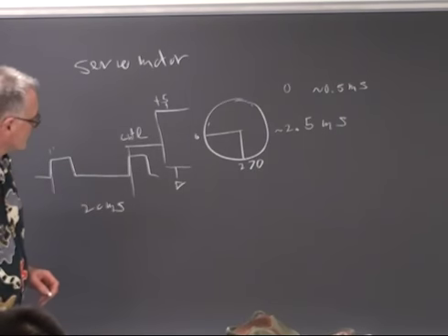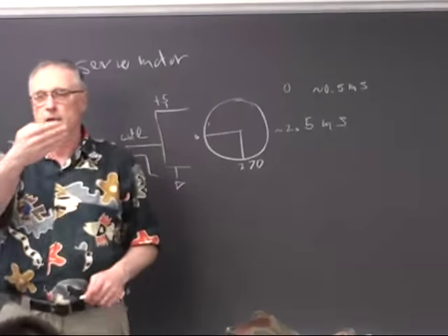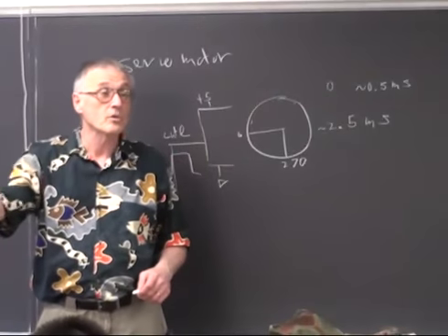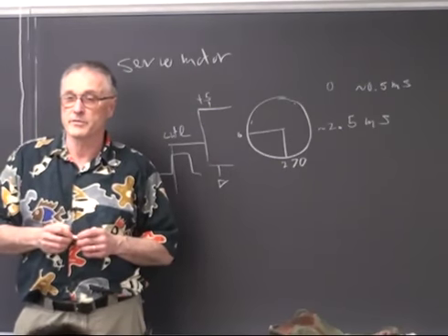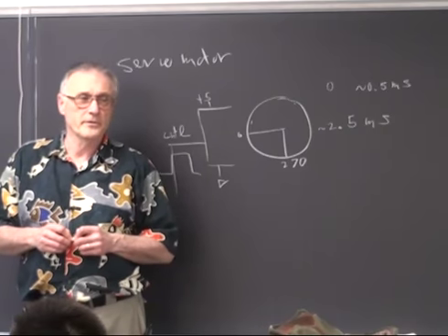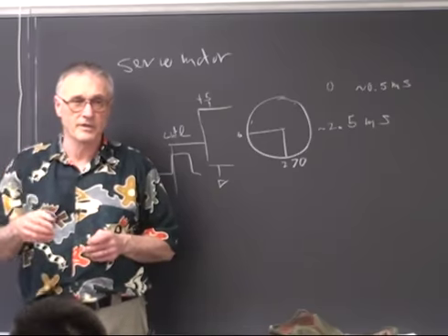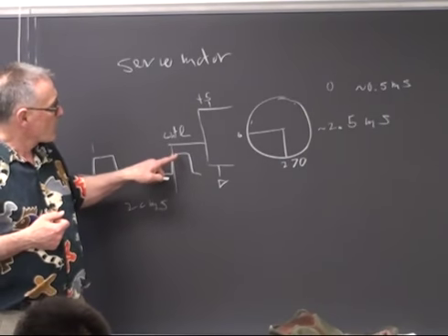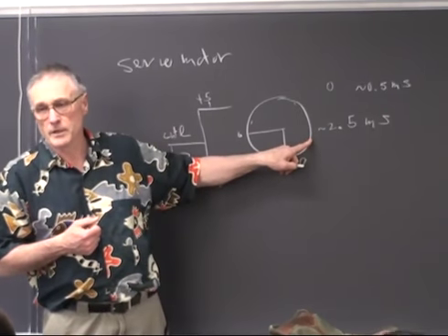And so if you need to, say, scan a sonar head through 180 degrees or something of that sort, then using a servo motor is a natural thing to do rather than trying to control a DC motor with position feedback. So in this case, the pulse length determines the shaft position.